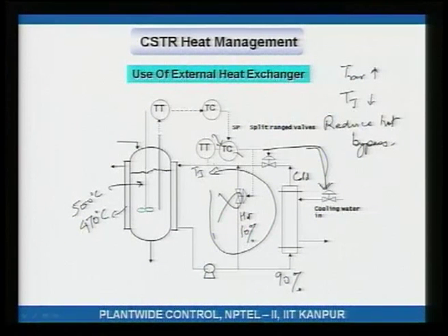To do that, the jacket temperature must be controlled tightly. For the jacket temperature to be controlled tightly, you must have this bypass. That is what gives you faster dynamics in the jacket temperature control loop. It is like mixing hot and cold streams. You can get the temperature immediately that you want, right. So, therefore, this is essential for reactor temperature control. Okay. I hope I have said enough on this.